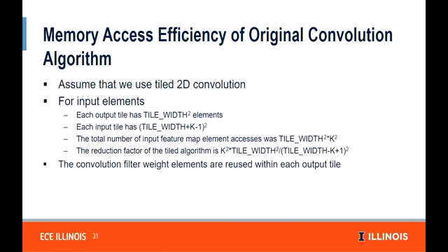So let's go into the memory efficiency calculation. I still haven't really answered it. I gave you a high-level reason why the matrix multiplication could be better. Because you have the tiled computation, and in the tiled computation, you can use the same input elements in the shared memory where you calculate multiple output elements of multiple output feature maps. So that's why the intuition is that you should be able to get better memory efficiency.